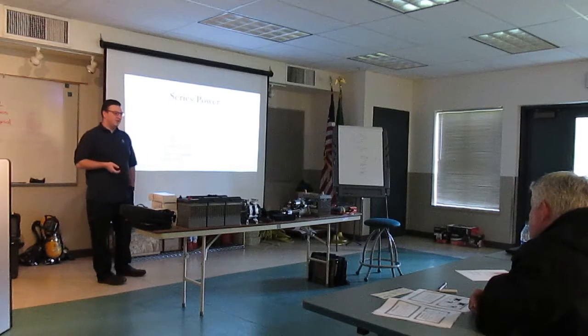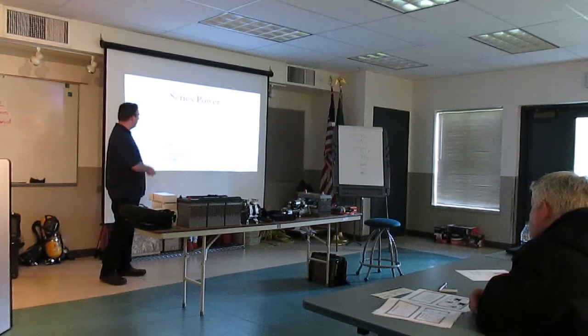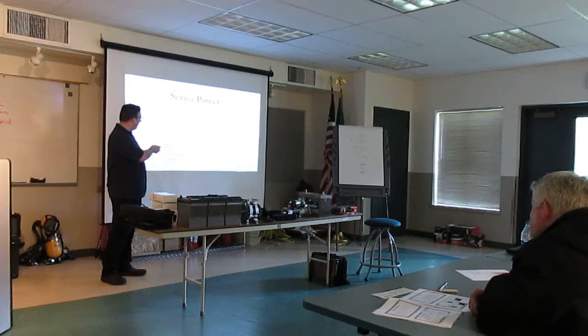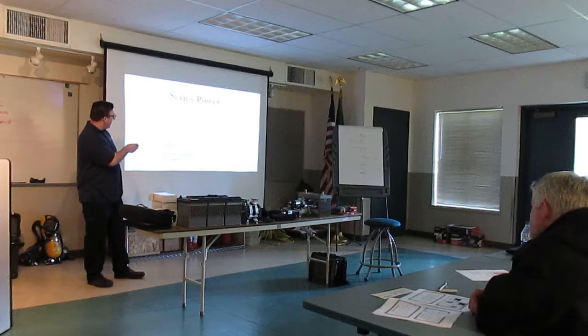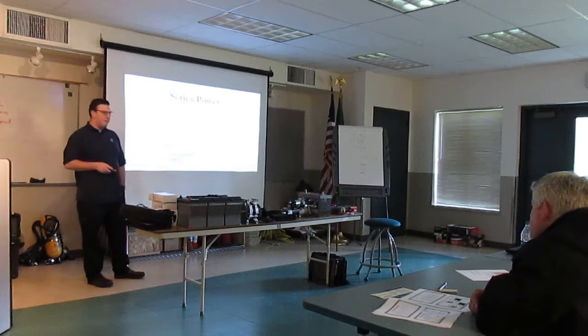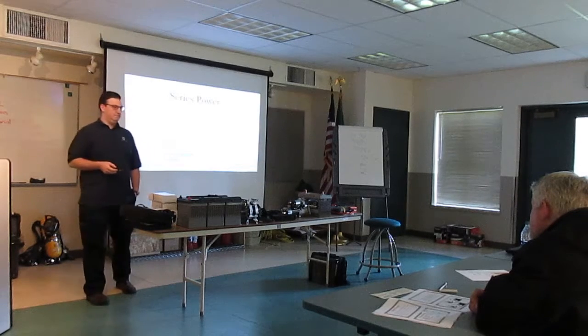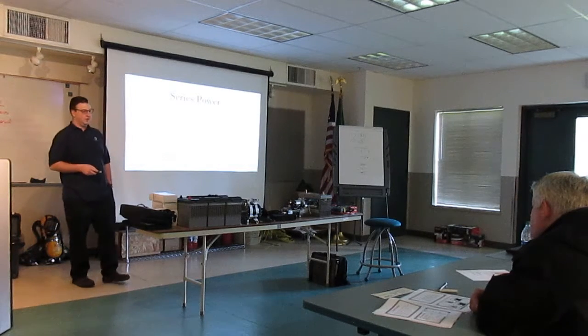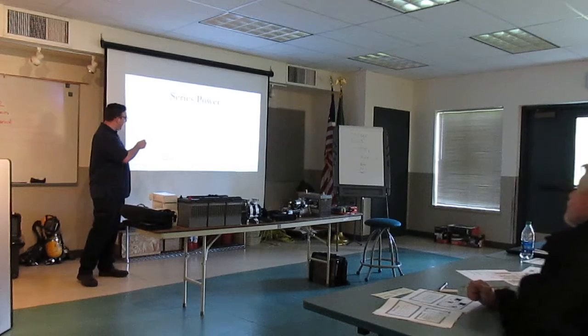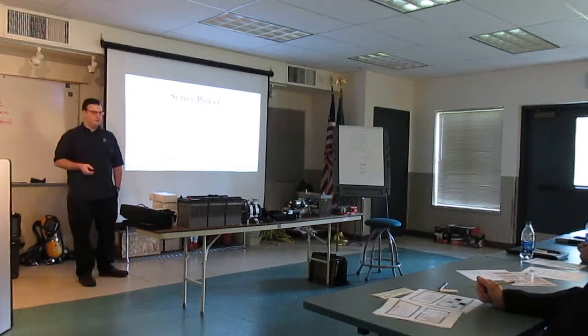Now, how do we use series most commonly on our batteries? Our series power. I have 2 12-volt batteries. I combine them, and I get my 24 volts. But you'll notice my current, even though I have 2 1,000 amp batteries, I still only have 1,000 amps to use. So when you're looking at 2 batteries to create your 24, or 36, or however many they run in series with each other, your voltages will add, but your currents won't.